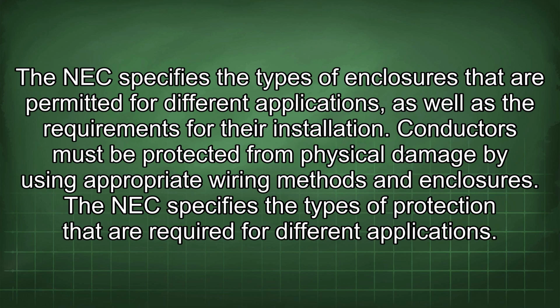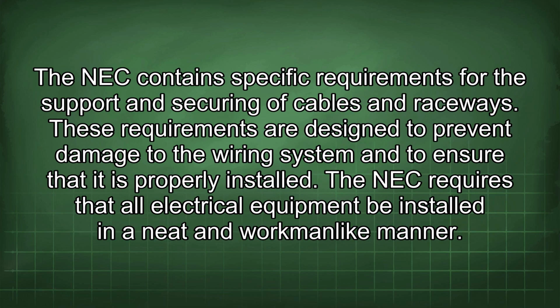Conductors must be protected from physical damage by using appropriate wiring methods and enclosures. The NEC specifies the types of protection that are required for different applications. The NEC contains specific requirements for the support and securing of cables and raceways. These requirements are designed to prevent damage to the wiring system and to ensure that it is properly installed.